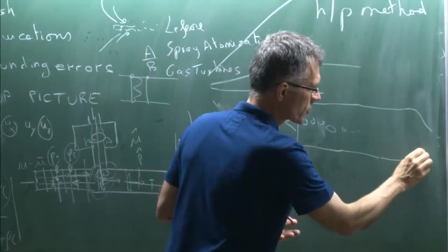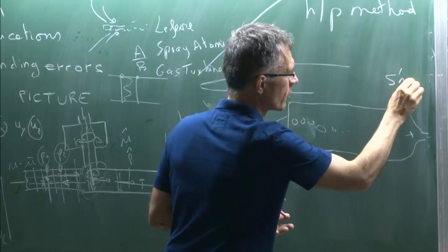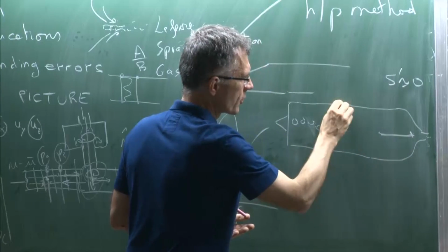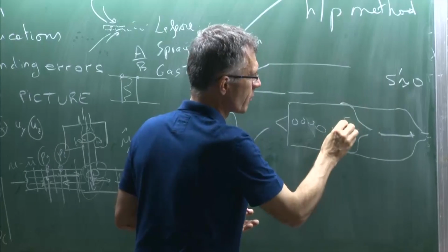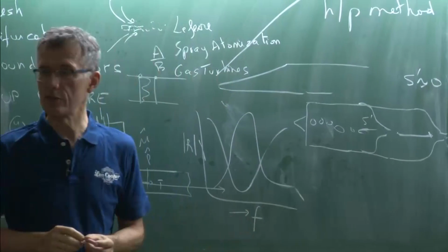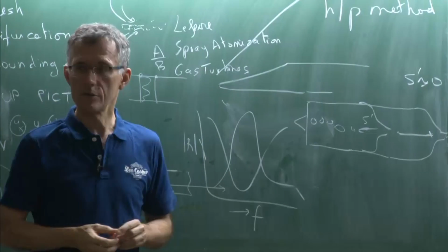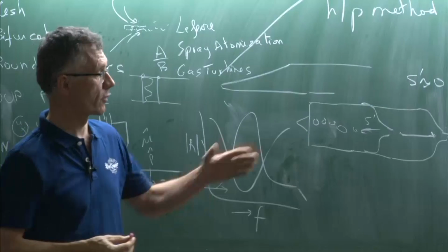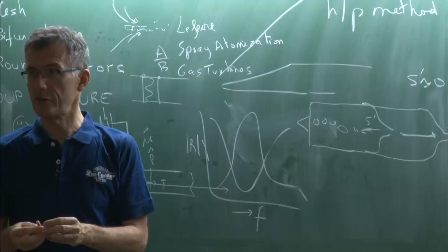If the chamber is long, by the time you reach the nozzle, the entropy wave will be almost equal to 0. As soon as you make it shorter, you increase the possibility of having an entropy wave reflecting on the nozzle. So yes, when you make them shorter, you have entropy wave problems. But also, you cannot make them too short. You need to burn. You need to preserve the efficiency.